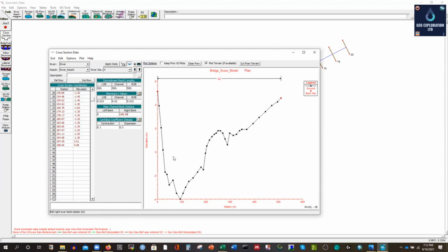And why are we just running this model for steady state flow condition? Because we don't need to run the model for unsteady, and the location of the bridge is another point. If there is no tidal condition, if there is not that effect of unsteady flow, meaning if the flow condition is constant, that is more effective, right? And if you can change it to unsteady, not a problem. But in most of the cases, if the run condition is simple, we can do that.